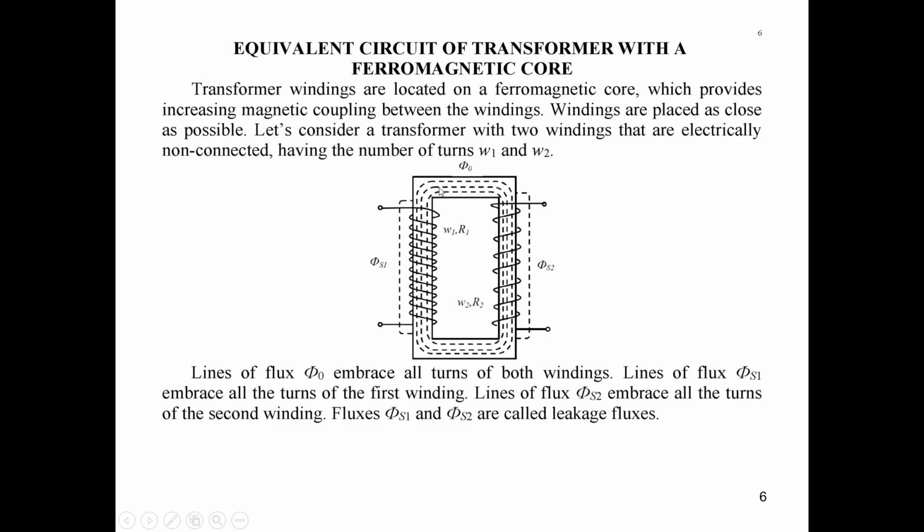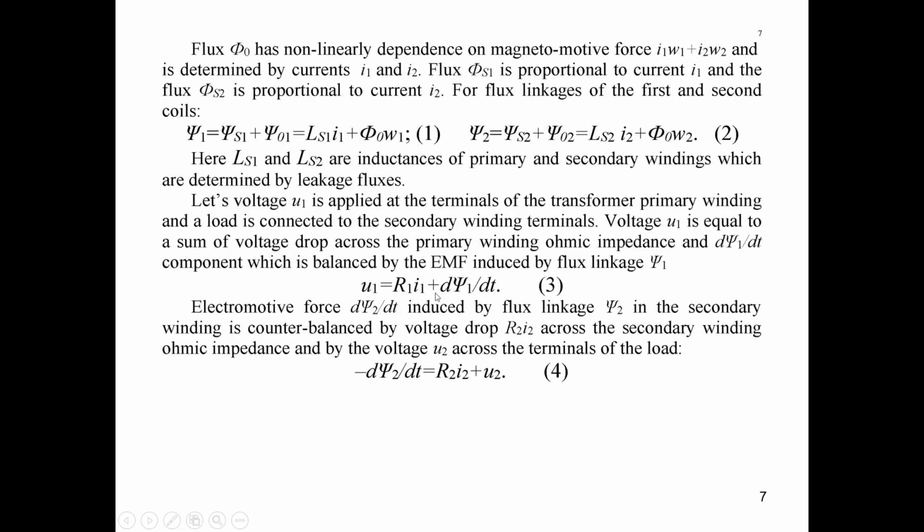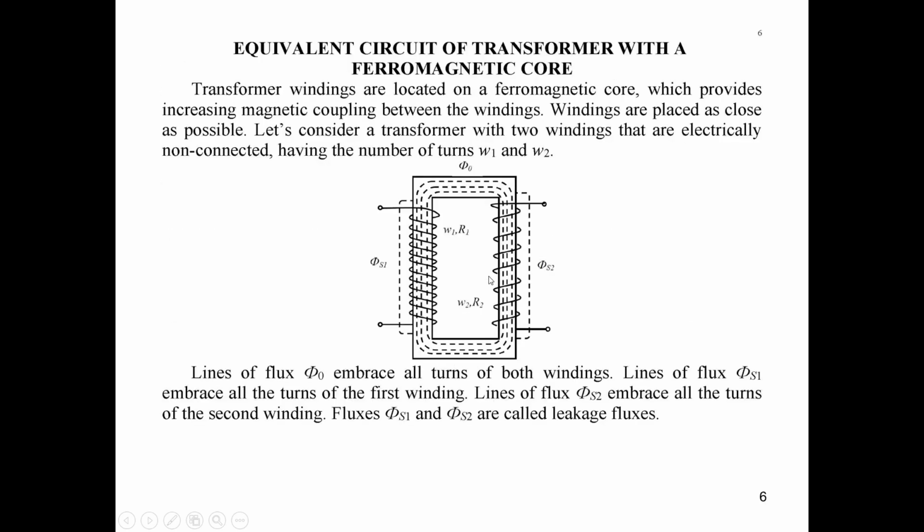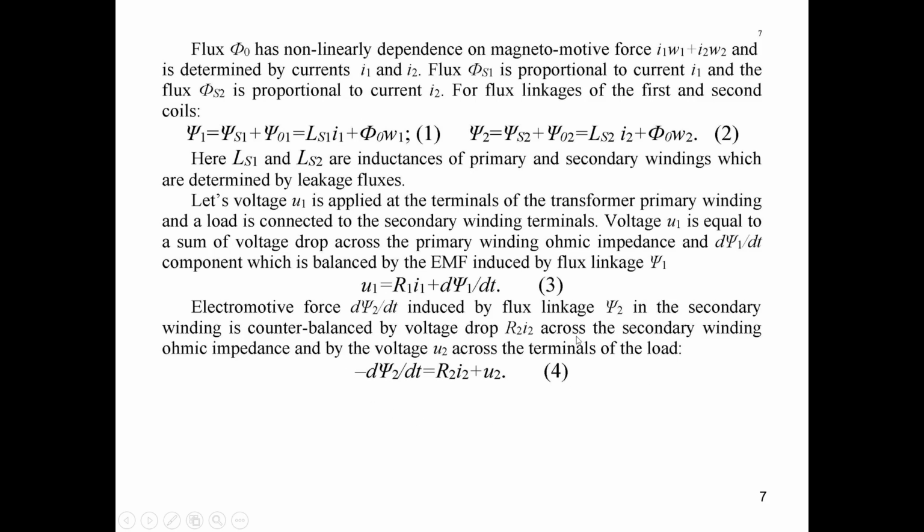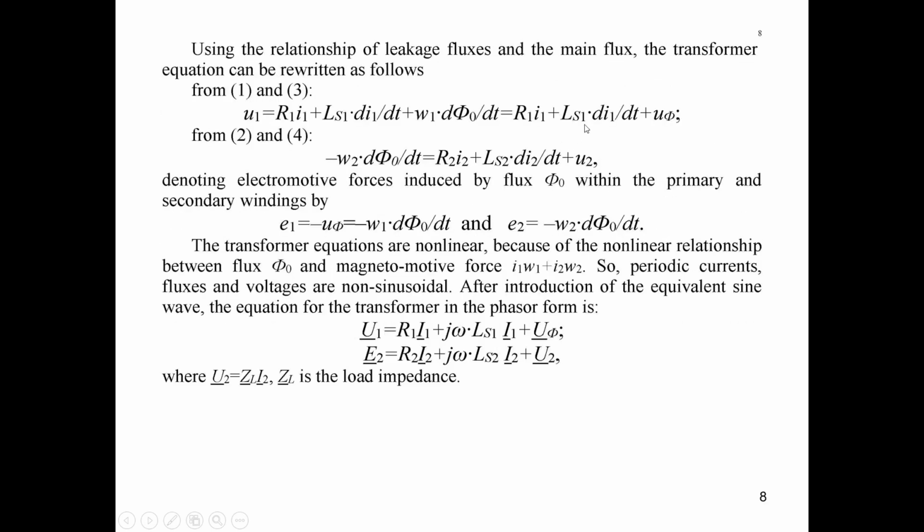permeability on the level of applied currents and applied voltages, and we write down equations which depict the connection between applied voltage and current in the primary circuit, then in the secondary circuit. As we have a common flux phi0 in the primary and secondary circuit, we write it down with such designations, and then we try to consider this nonlinear